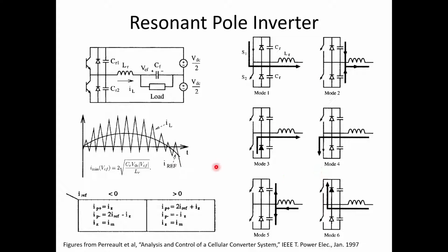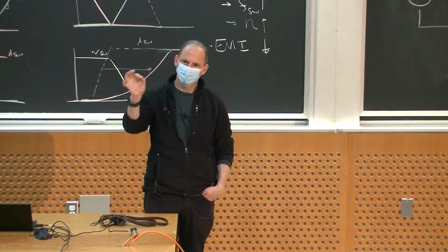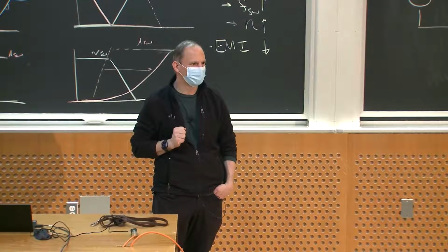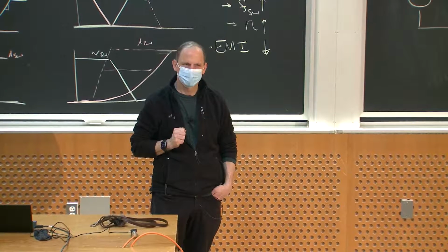So usually when you look at this kind of circuit, you say, okay, when the device is turning off, it's loaded by some impedance that typically looks inductive, or basically is carrying a current in a direction that will help charge those capacitances in the right direction to give you soft switching, is the way to think about it. Questions?